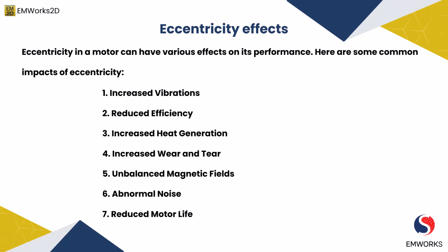Next, we have abnormal noise. The imbalanced magnetic forces and mechanical stress caused by eccentricity can produce abnormal noise during motor operation. Unusual or increased noise levels can indicate the presence of eccentricity and can be a warning sign of potential motor issues.